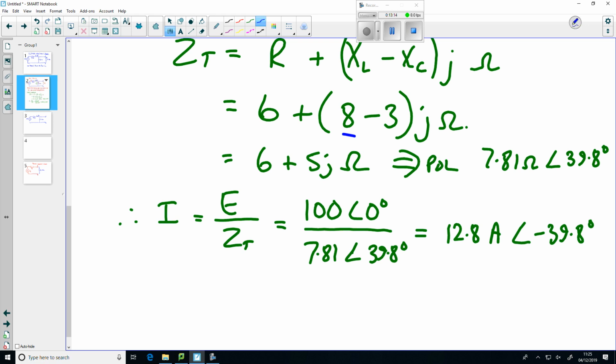Yeah, it's got capacitance in it as well, but overall that's inductive. So using that word CIVIL, we've got an inductive circuit, the current's got a negative angle, that's lagging the voltage. Yep. So that's a useful little check that you've done that complex division properly. Yep.